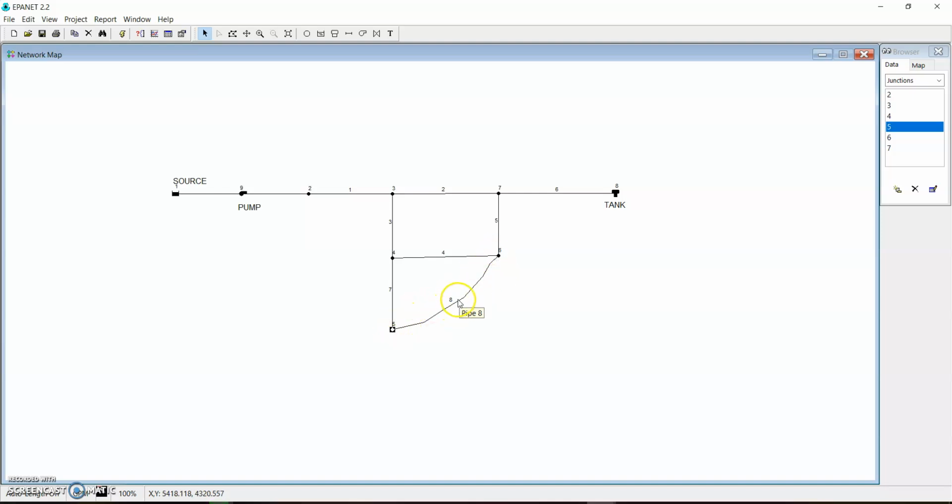So for you to straighten node 8, you can just click on it and then click this button so you can see the clicking points. So you can try to drag and move around with these points to ensure that you have it a bit straight, right? So you can move, and if you need more, you can always move. So let's see, at least it's a bit straight, right?